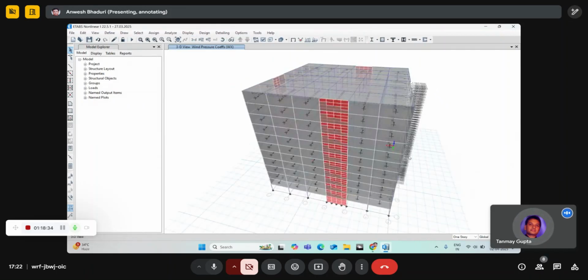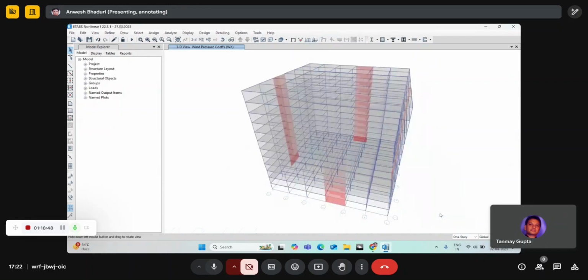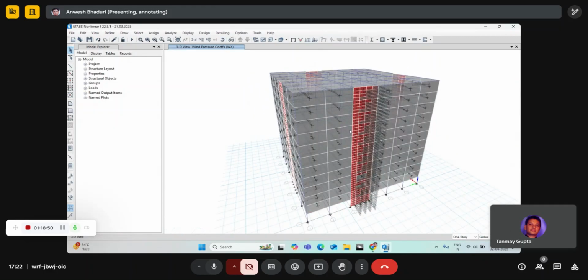Does the cladding need to be removed, or can it remain? The cladding can remain since it has a none property. It will not affect the analysis results. So this is how you can apply the wind loads either from diaphragm or shell objects. In diaphragm, your sides are taken as constant, whatever is there in the leeward. Here we can change that.